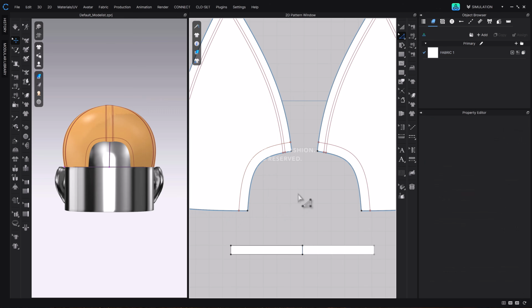Before sewing the bias tape onto the back opening, we need to separate the areas where the pattern will shrink from the areas where it won't. Usually areas where multiple layers of fabric overlap don't shrink easily. So, for parts where the sweatband and snaps are attached, as well as where the seam allowance and bias tape are sewn, you should do one-to-one sewing. The other areas can shrink naturally during sewing. To achieve this, we'll add segment points to define the exact length for the one-to-one sewing.